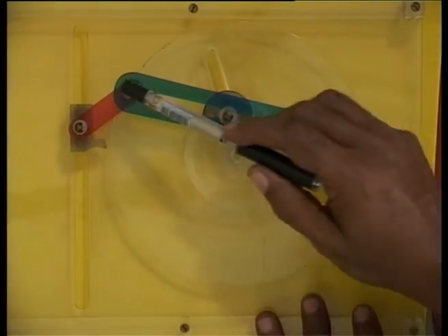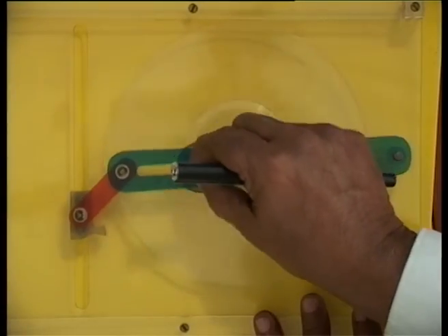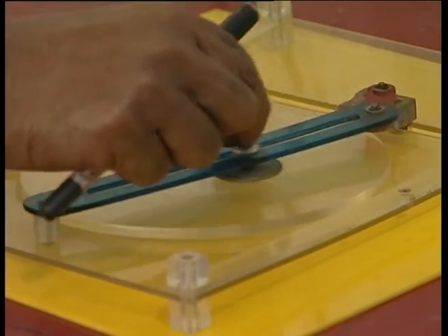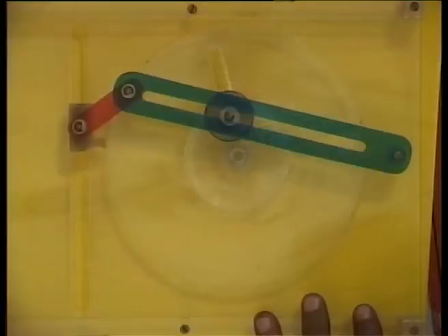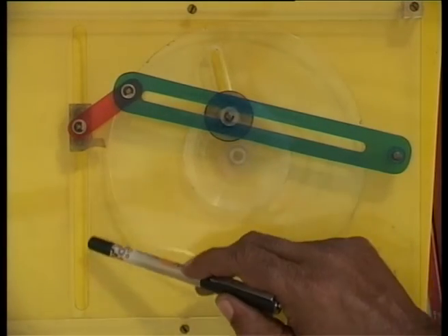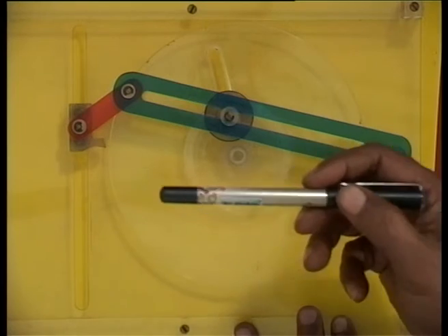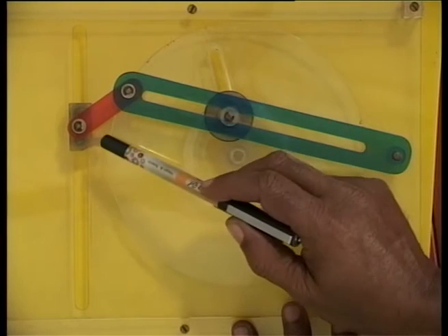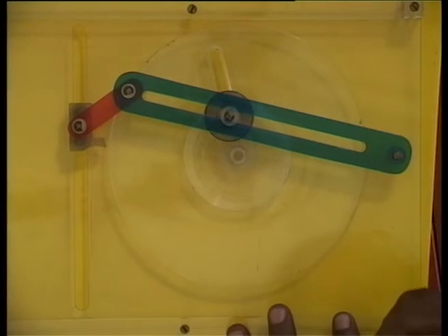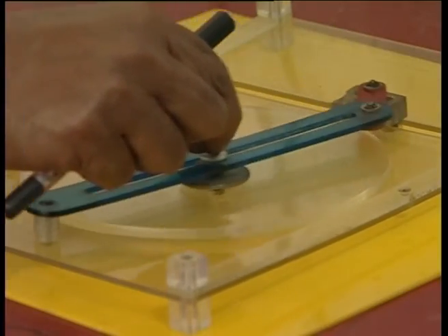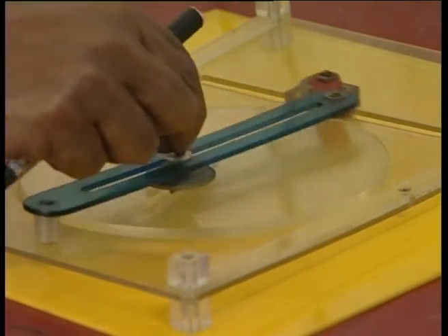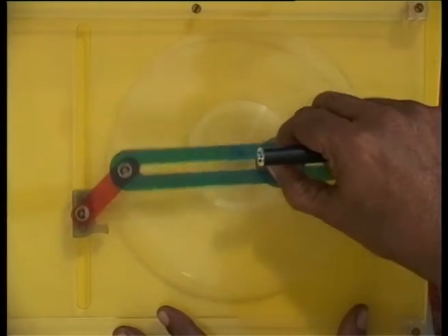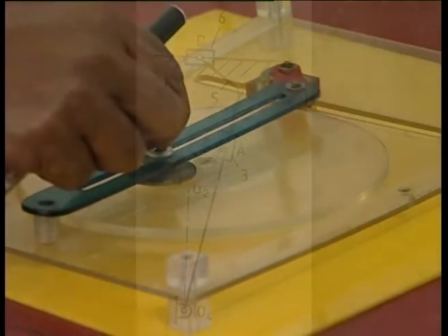So, we have a 6 link mechanism here, where the continuous uniform rotation of the bull gear is converted into the to and fro motion of the cutting tool. Now, the cutting tool during the forward motion is doing useful work, and we have to maintain a proper cutting speed. However, during the return stroke of the tool, this is not doing any useful work. So, I would like to make the return faster, and that is why it is called quick return mechanism. As is seen very clearly, if I rotate the bull gear at almost uniform speed, the forward motion is slow, but the return is faster.